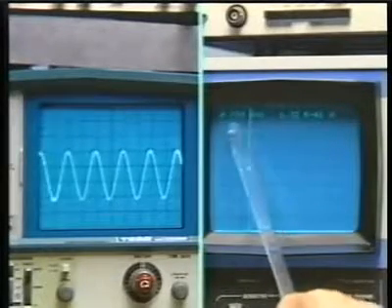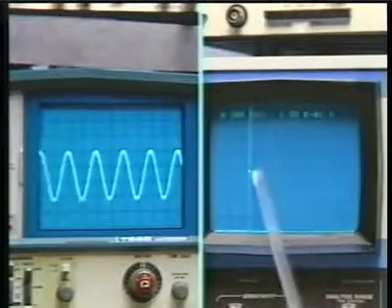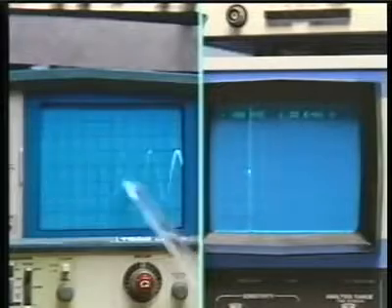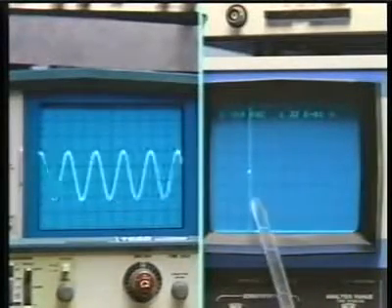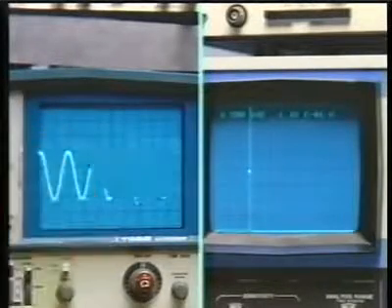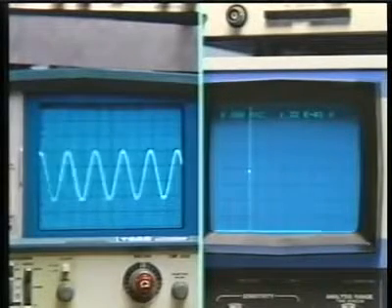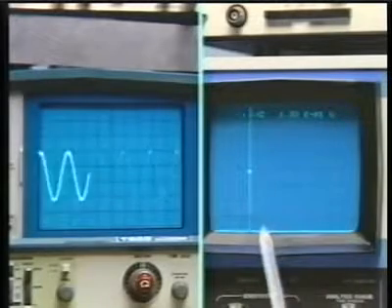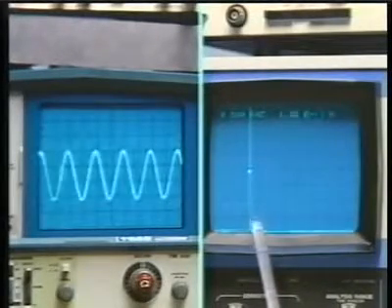And we can read out, in fact, that it's 500 cycles. And this is the amplitude. And, of course, you could verify the frequency also in the time domain display simply by measuring the frequency or the period. This is set at still 1 millisecond per centimeter, so that is 500 hertz. Okay. Well, now maybe what we can do is vary the frequency. Let's vary the frequency of the sine wave generator. Maybe also listen to it. I'll turn on the tone, yeah.